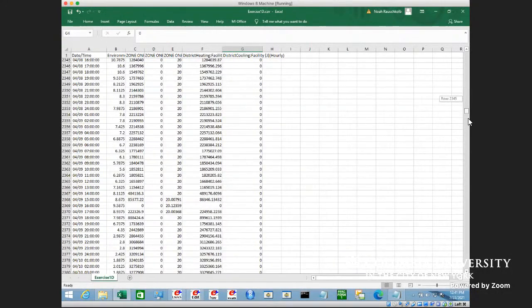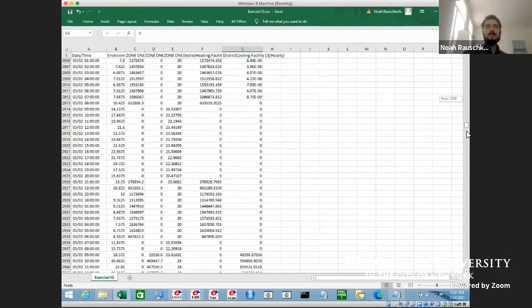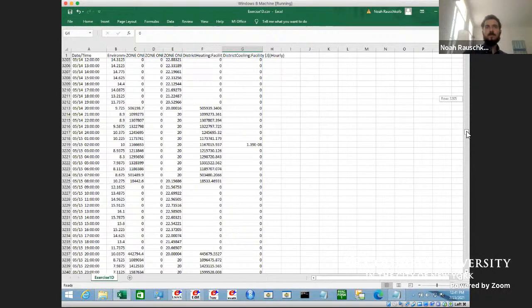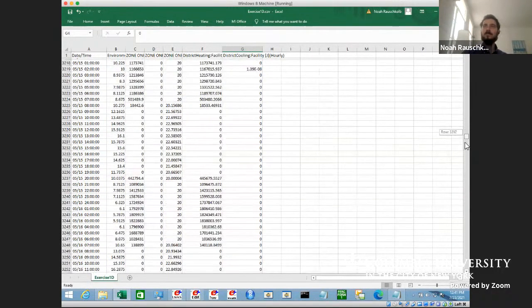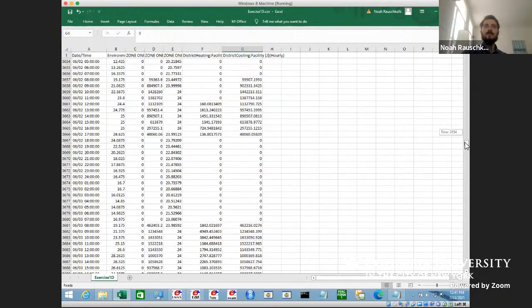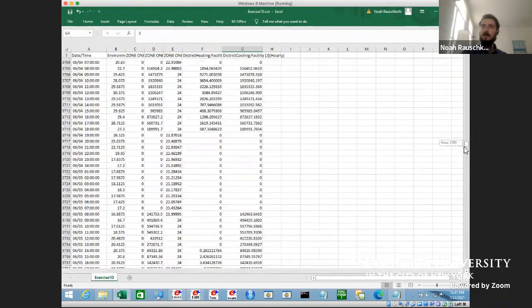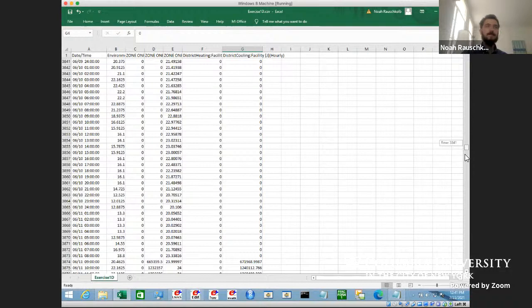What systems have you put in now in this? This is an ideal loads air system, which is basically an abstracted heating system that can do whatever it needs to do without any constraints. So it's really just a way of computing how many BTUs you need to be putting into the space or taking out of the space, without any constraints on how that actually works.